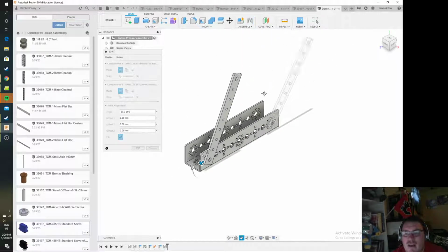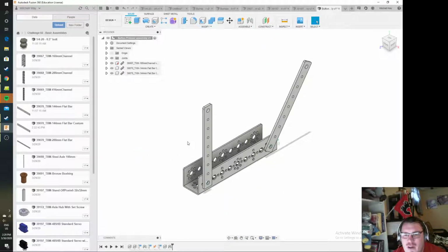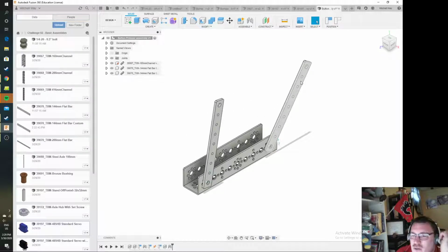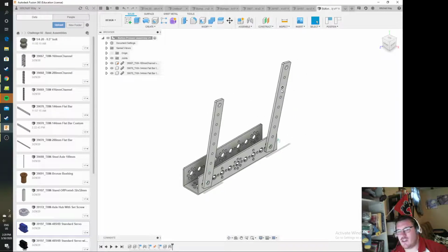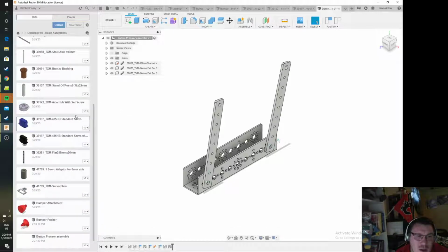Now you'll notice right now that I'm actually attaching things, though in reality I'd probably have brass bushings, I'd have bolts, things like that. It's not a bad idea to build the basic mechanisms this way before you get to those more minutiae things. I can prove at a high level that this design is going to work before I put the bolts into it. That's really powerful because I might be able to modify the design and design around something or potential problems if I need to beforehand.